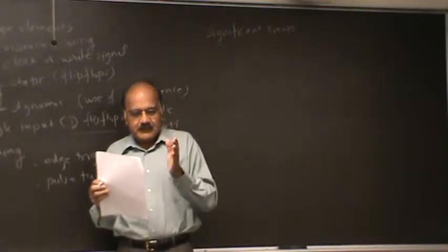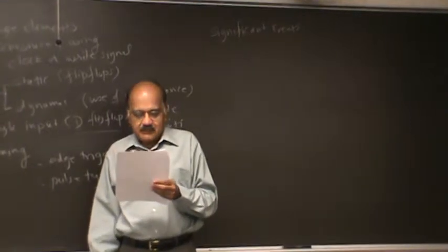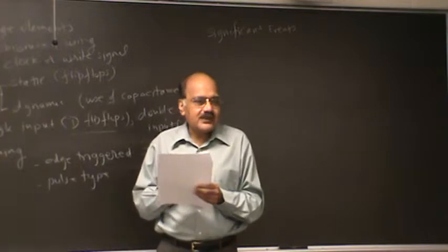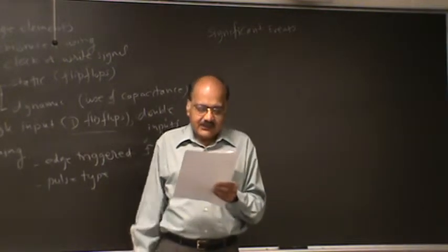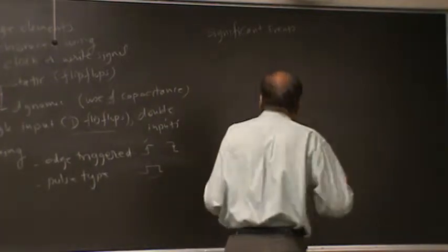So sampling will be done during a fairly short period of time, perhaps during a rising edge. Now during the time of sampling, whatever is being sampled is required to be stable. So you need to watch for this.